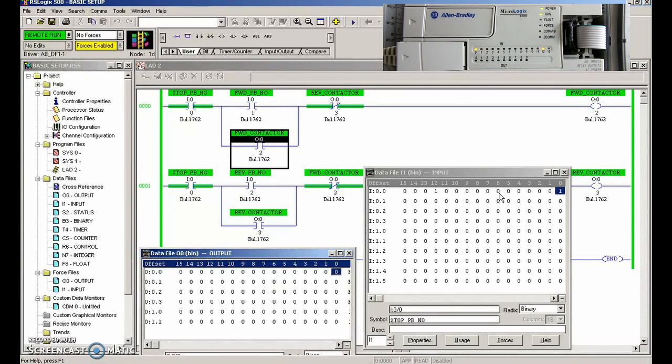And somehow bring that in part of our program so that if we're in an overload state, here, let's do that. Let me just trip the overload for 2 seconds. Okay, so I'll get it going and forward now. And what I'm going to do is I'm going to trip the overload that corresponds to that forward contactor. And when I trip it, you can hear the contactor pull out. So the contactor has pulled out. Let's see if we can hold it there.